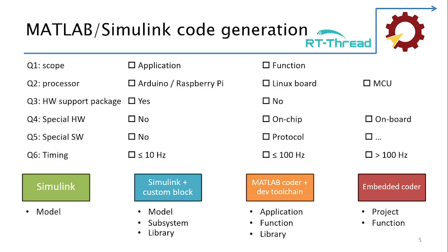There are several options for code generation inside MATLAB depending on your settings. Today I would like to go into the very basic idea of MATLAB Coder, because this allows us to make C or C++ code that can be combined with our base code, which may have other features such as a user interface, and we just concentrate on the processing part only.